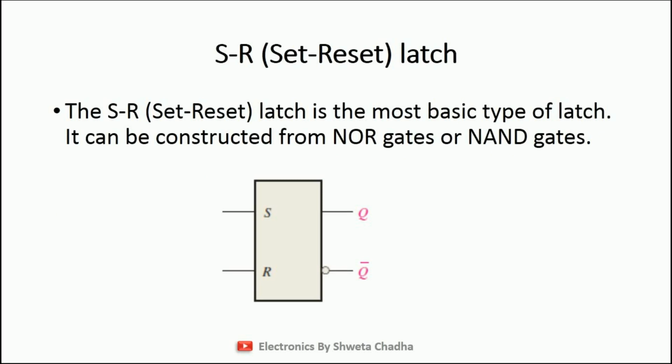Next is the SR latch. S stands for set. Set means 1. R stands for reset. Reset means 0. So SR latch stands for set-reset latch. The set-reset latch is the most basic type of latch that we have. It can be constructed from NOR gate or NAND gate, and as already mentioned, I will be discussing both types in this presentation.